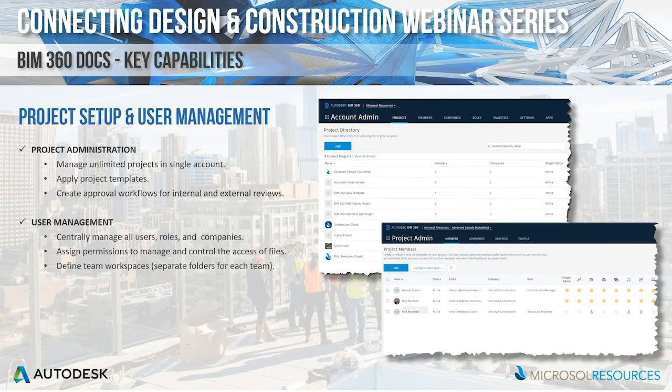So as far as user management goes, BIM 360 is actually designed to be used with third parties, so consultants, other firms. So, we're given the capabilities to essentially manage all of our users, their roles, and the companies they're associated with, all within BIM 360. The first thing you would do is add members to your site and then invite them to a project or projects. You can assign preloaded roles to your users based on their station in the office hierarchy. But more importantly, the roles themselves have different folder access permissions assigned to them. Again, we'll get into all of this here in a minute.